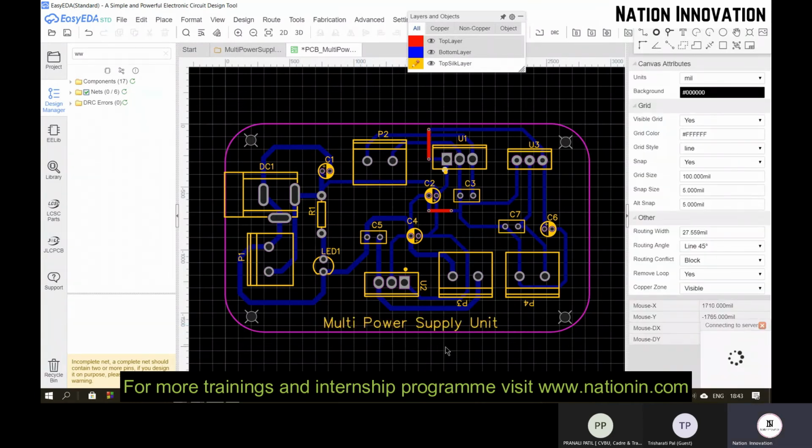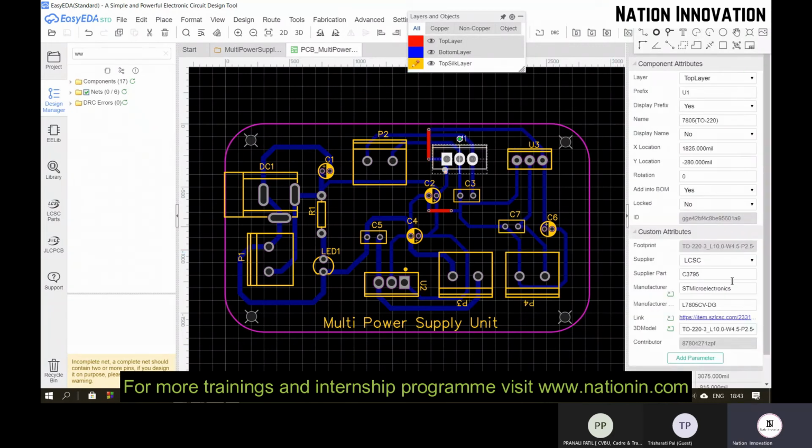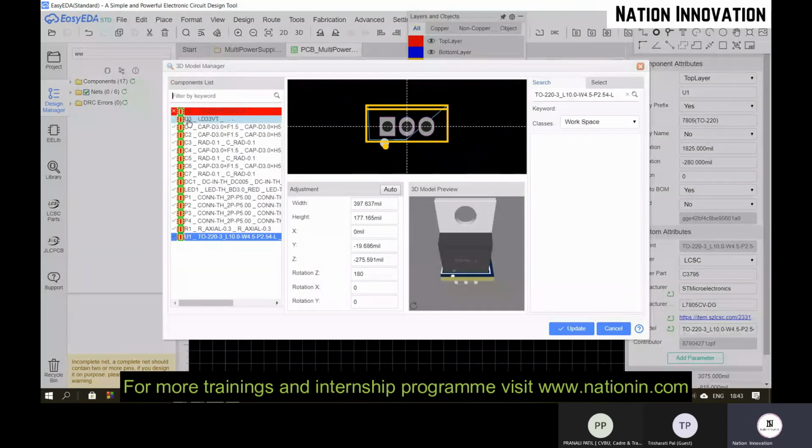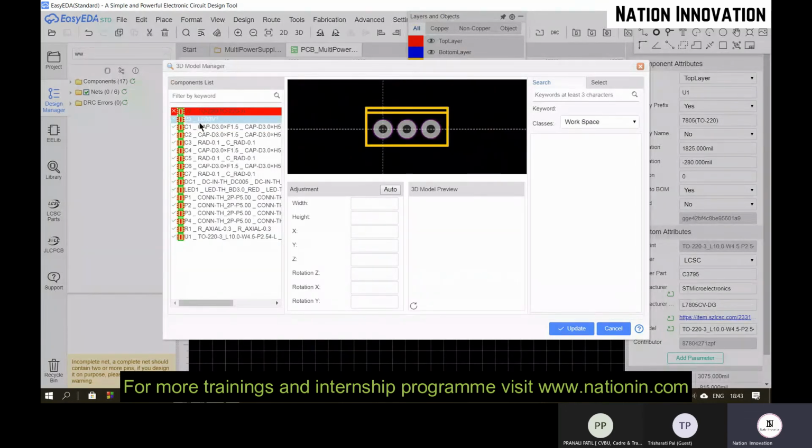Okay, then save again and select any one of the components and go to the 3D model. Whatever cross mark is shown here means that the component has no 3D model. So select that component and in the search you can type the part name like LD33. In the user contributed models, there is no 3D model for this LD33.